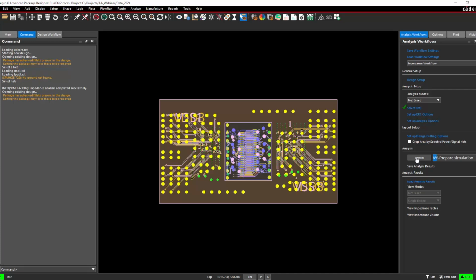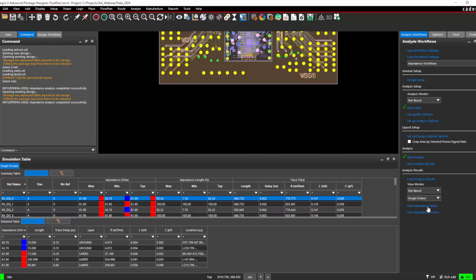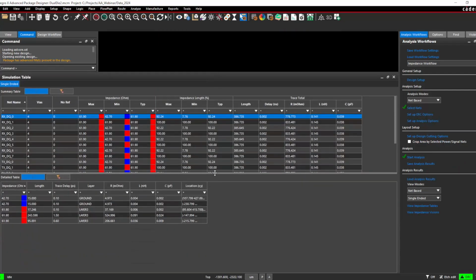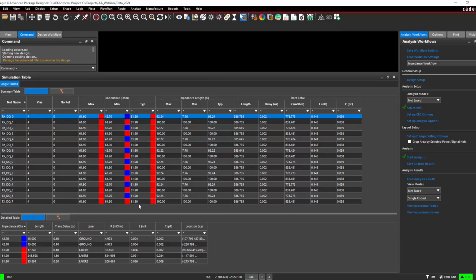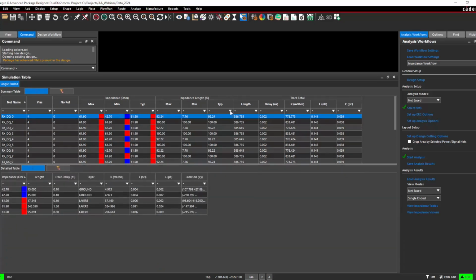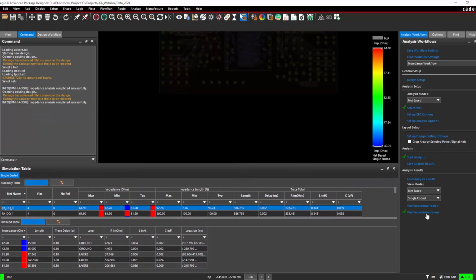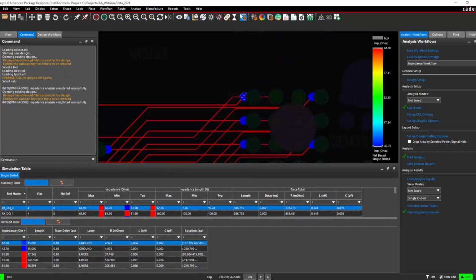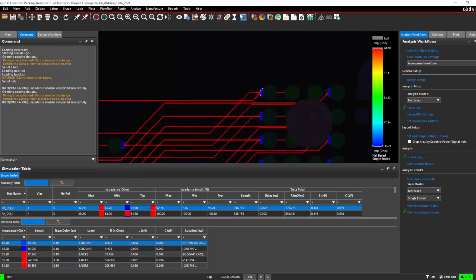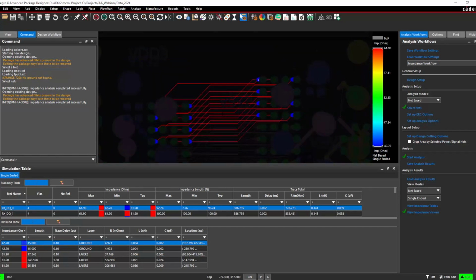And when the simulation completes, we should see indeed, based on the better referencing, let's go ahead and pull this up a little bit. We can see that our typical impedance is consistently the 61.9 ohm value. And there are some excursions outside of the 61.9, and those events are the result of fillets and lead-ins to vias. That's the purpose of the typical column, that it ignores those brief excursions. Okay, so we solved our impedance issue.